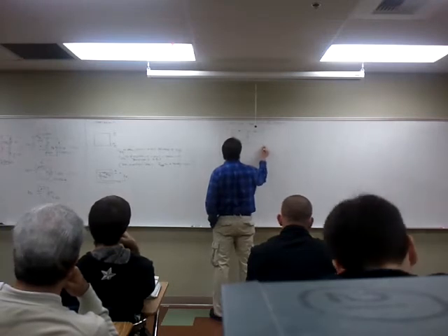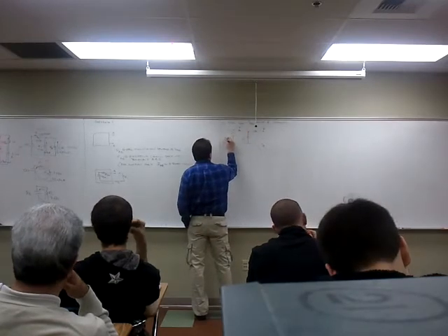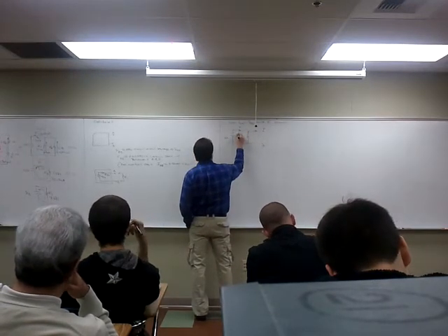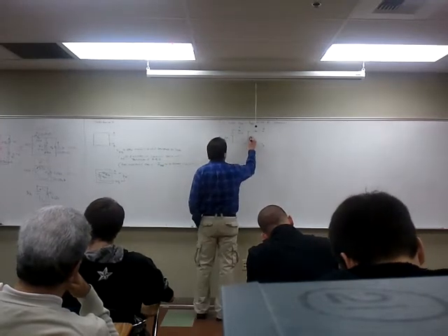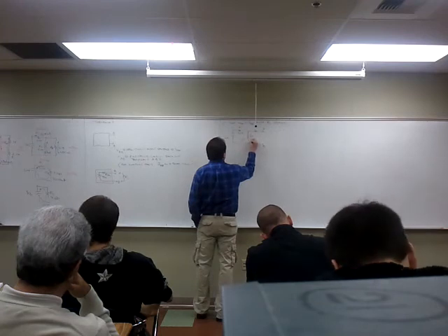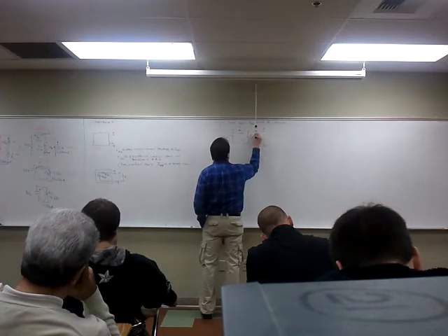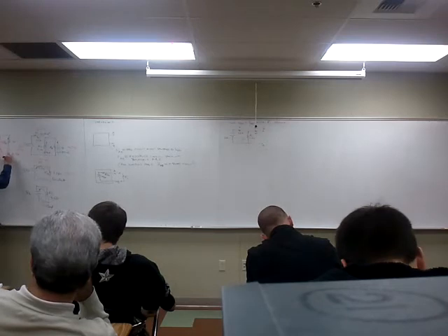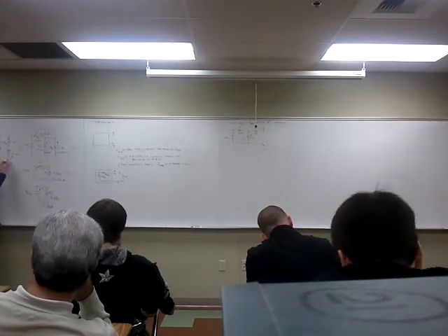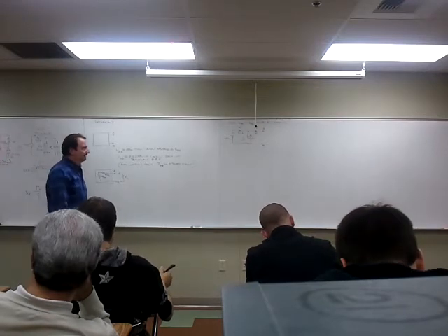And you label the terminals where you remove the load, A and B, arbitrarily. So this 2.7K that I labeled RL, I remove it and I label the terminals where I removed it, terminals A and B. So on my schematic here, it's like just erasing that for a moment. And we're going to put it back in later.